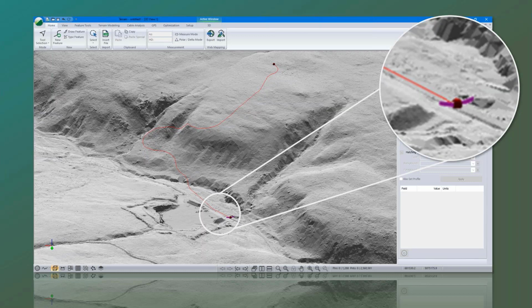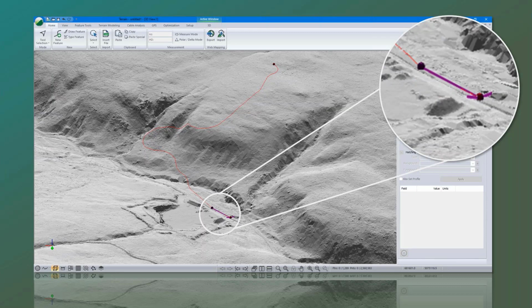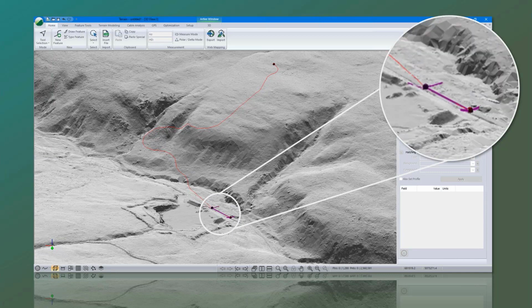Once we've got a cross-section established, we'll measure from that first station to our next station. And that next station usually is located either as far as we can see, or somewhere in between as far as we can see and where we want to go to capture something notable. Usually that something notable is topographic features, but it could be other things like ground type changes, etc. Once we get to that second station, we're going to collect cross-section information again, and we're going to continue to do that until we get to the end of our road.